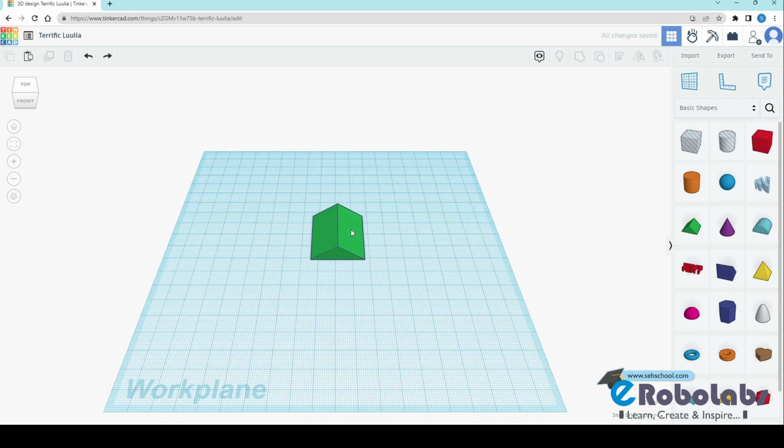Okay. So the next is ruler. To access the ruler command, click on ruler in the panel on the right of the TinkerCAD screen or press the R key on your keyboard. The L-shaped graphic appears on your pointer on the screen.